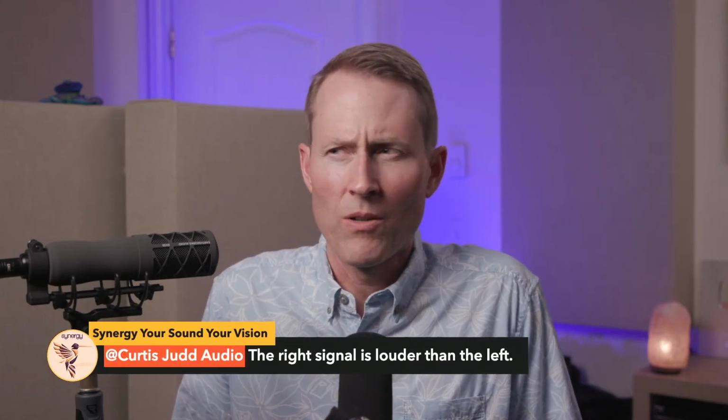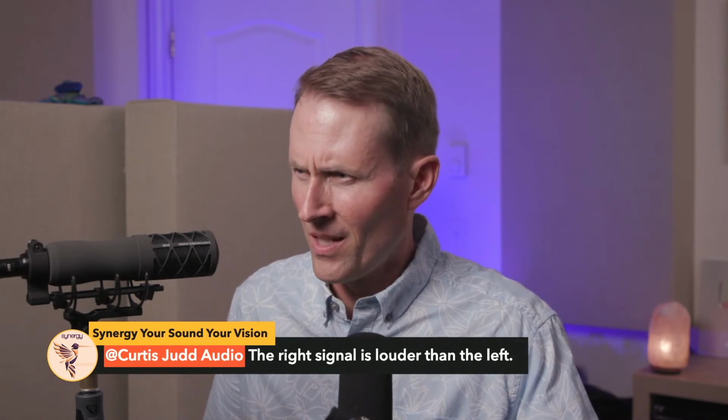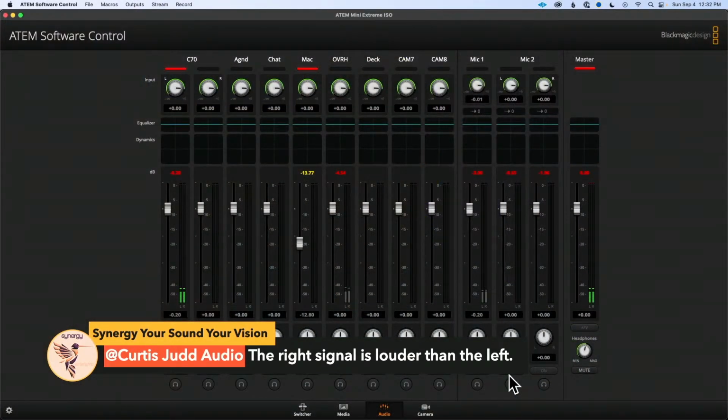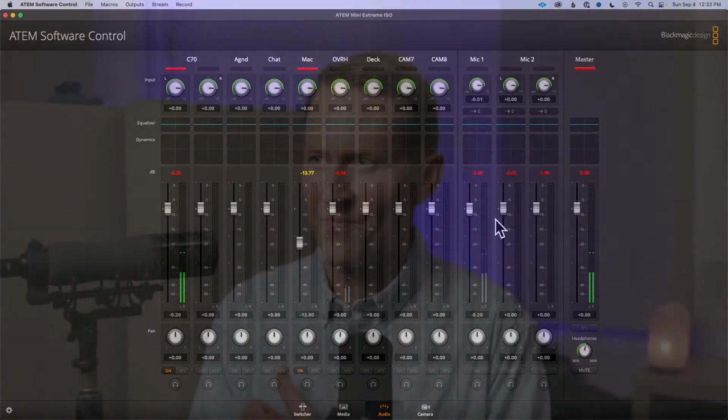The right signal is louder than the left. Yes, that is a little funky thing with, let's go to the Mac here. You'll notice here as I talk, notice these signals right here. They're kind of hard to see, but one is louder than the other just slightly. It's because the detent on the pan control is just a tiny bit off. It's one of those funny things about this particular copy of the mixer. If I tweak it here just a little bit, now they're exactly the same. I don't know if that was what you're referring to, but yeah, the pan potentiometer is just a little bit off.